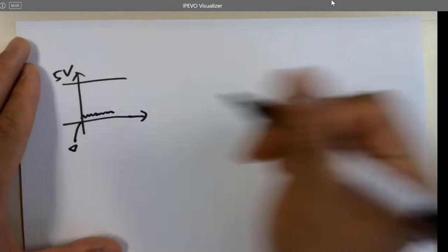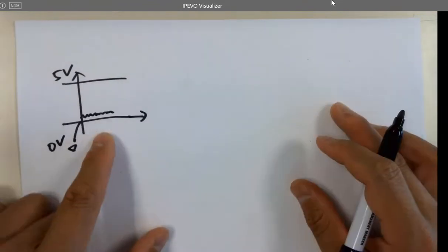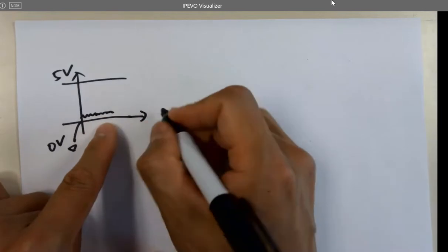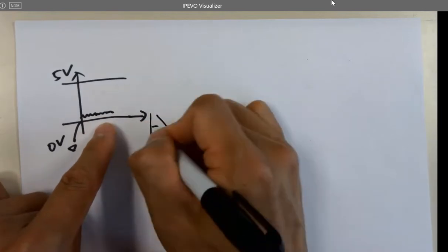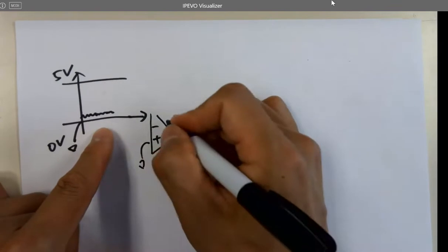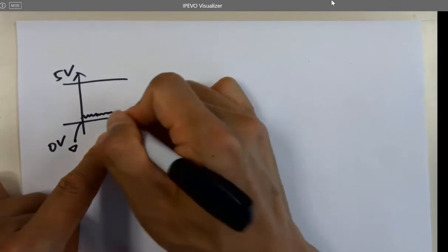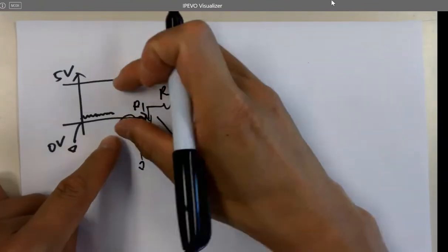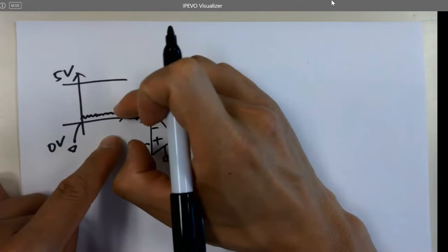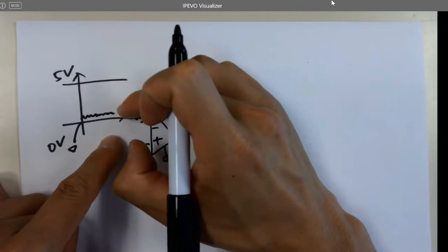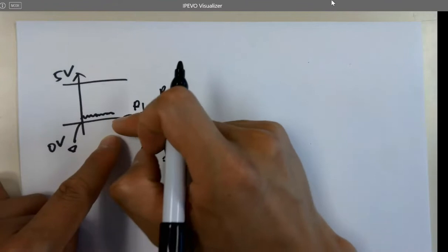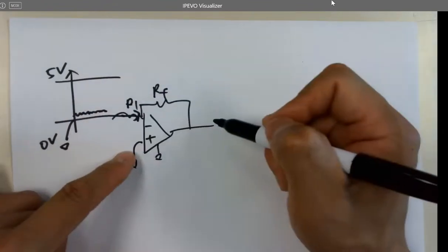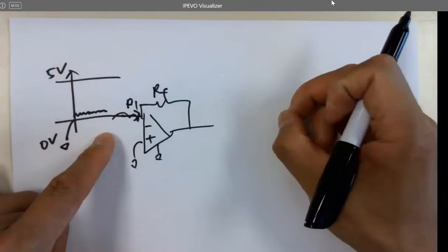Here's ground. And that's a signal output from the sensor. I'm trying to directly feed it into an amplifier. Let's just do it that way. What's going to happen? I have that whole range to amplify, to swing it, right? But now it's not ideal in the middle. It's swinging around something like 1.1 volt or something. If I amplify it, what's going to happen?